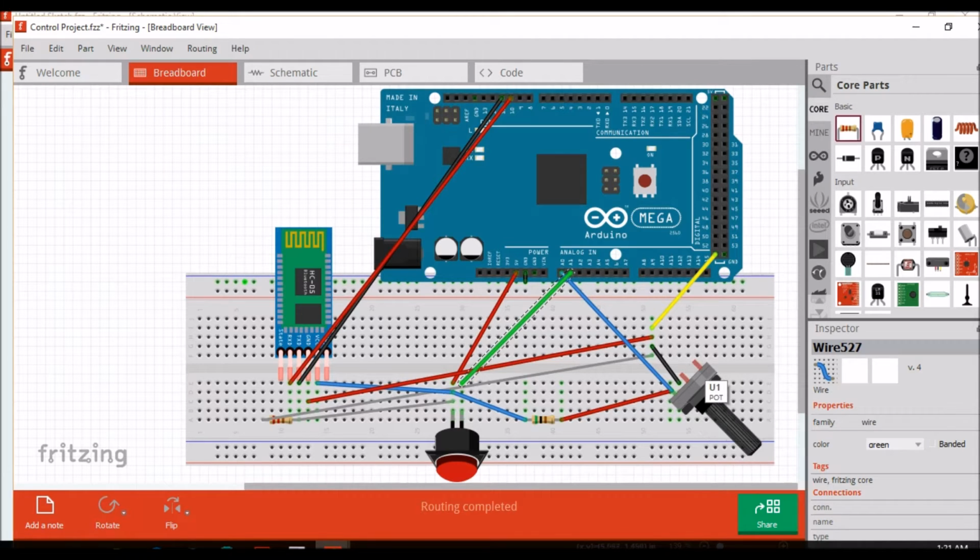So we can actually vary the resistance of this potentiometer by rotating it. We can vary its resistance within the range 0 to 5 kilo ohm. So when the resistance is increased, the total current through it will be decreased, and so will be the voltage drop across this fixed resistance. So if we measure the voltage drop across this resistor from A0 pin, it will show a decrease in voltage reading from this analog read pin.